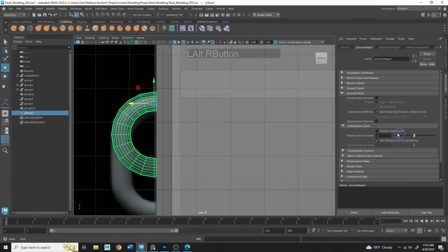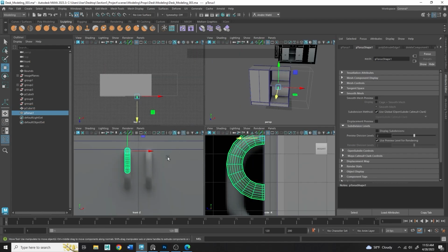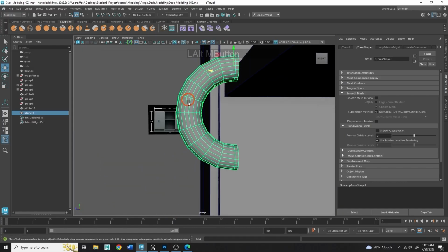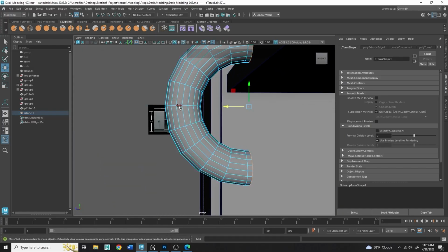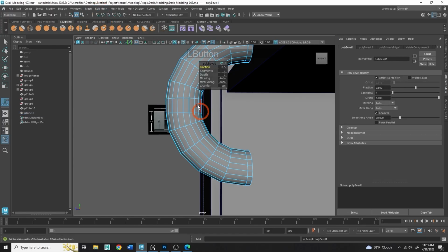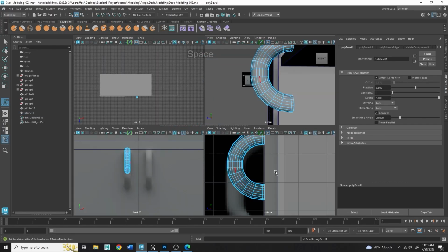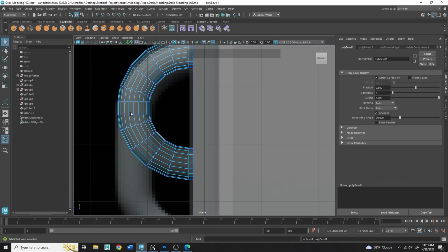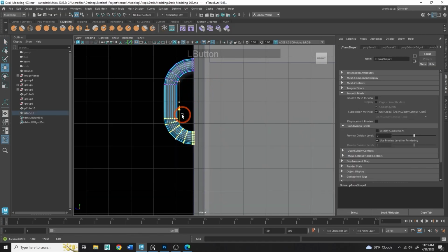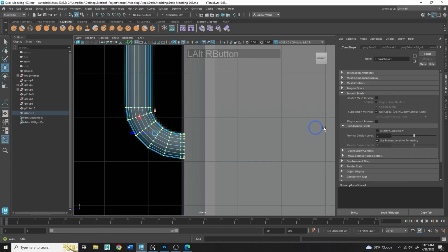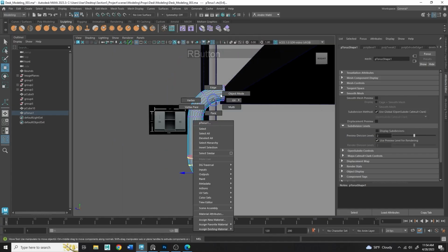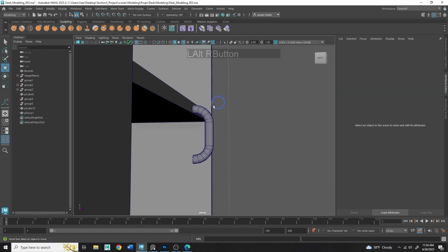And there you go. Now, to get this to split correctly, I want to use a bevel on that midsection, just like I demonstrated with the chain. I'm going to double click there, Edit Mesh, Bevel, and now we'll have a straight line on either side. And what I can do is grab the bottom vertices here past this point with a marquee select and just pull that down to match the handle's placement. And just like that, we have a nice little handle for our object.